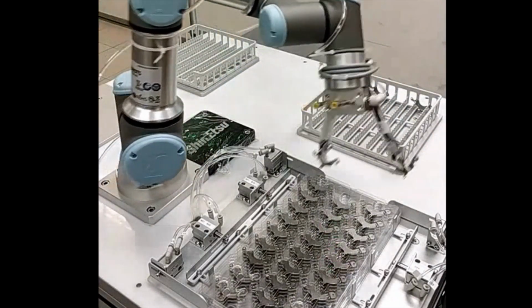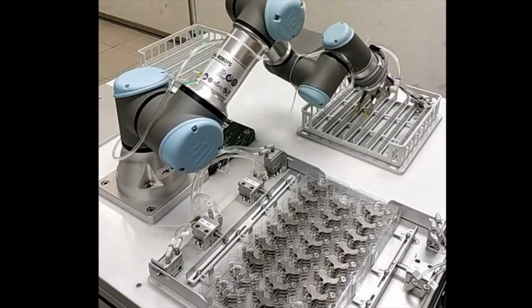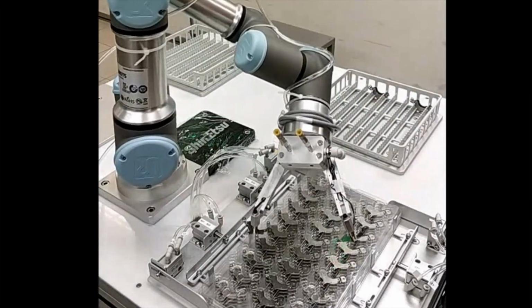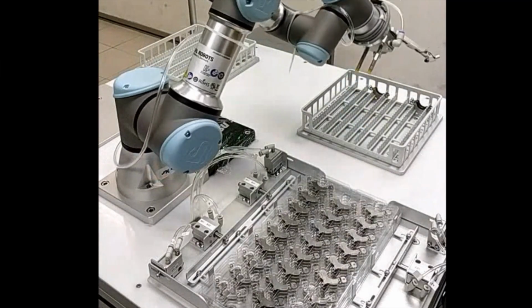The articulated robot is versatile. But versatility has a cost. Do not select it for handling objects that are lying flat or processes that do not require orientation changes. There is almost always a faster and simpler option for those.